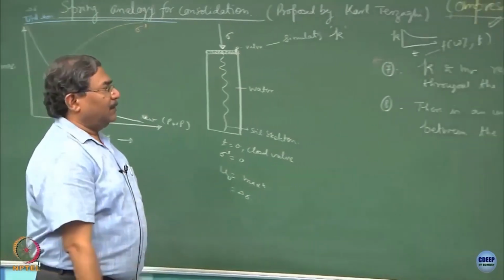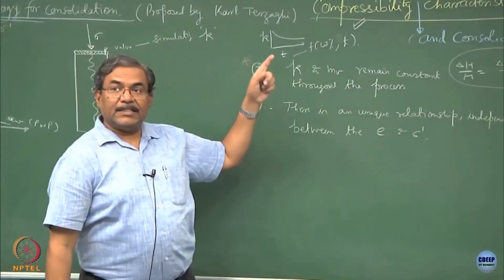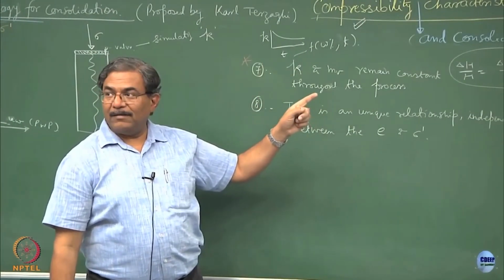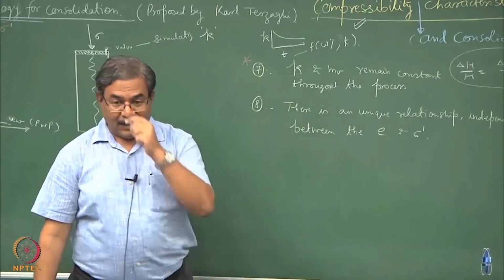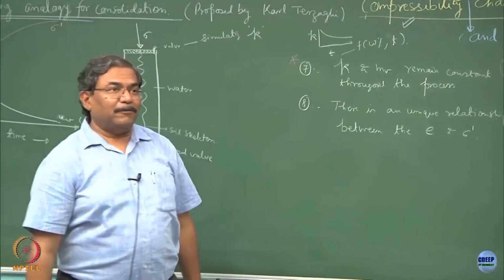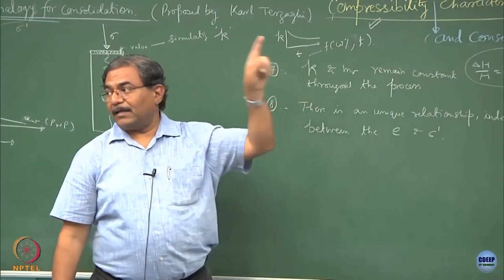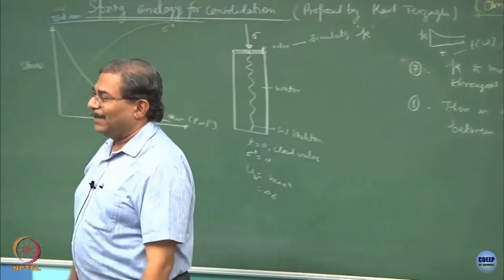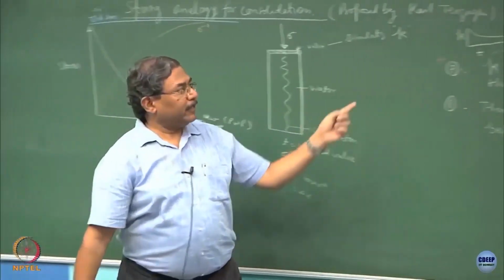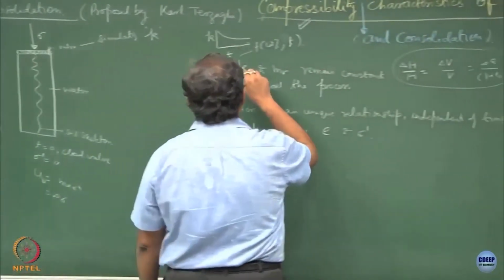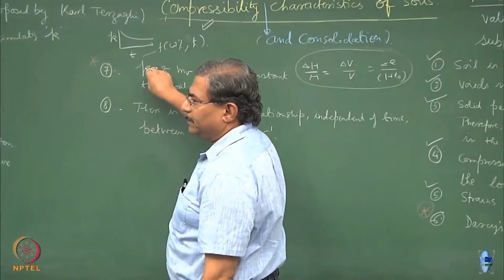There could be changes at the pore level which might occur. Depending upon the type of contaminants which you might be dealing with, the K might increase with respect to time. With bacterial activity, K might change with time. So, it is not a good idea to assume K remains constant.